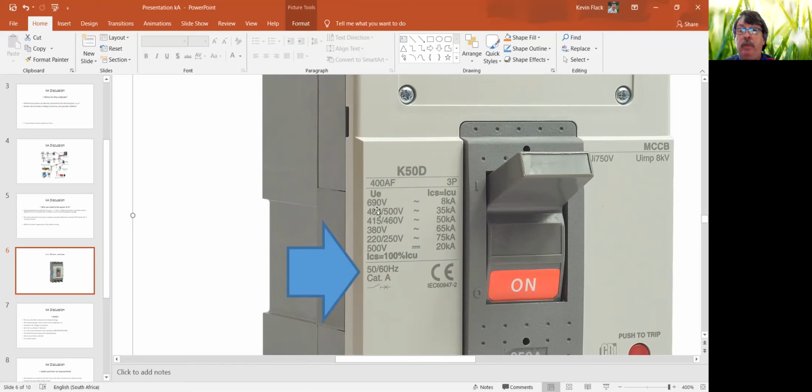type of thing. So this particular breaker will be tested at 8 kA. It will trip. It will be closed back into that short circuit, an 8,000 amp short circuit. It will trip, and it's very much toast thereafter. It's going to pass some rudimentary tests, typically something like the 8 kA test is going to be a trip afterwards of something like 200%. It's going to get pretty warm. It's really just survived. It can survive that, but that's the test. It's put through a routine of tests after that.